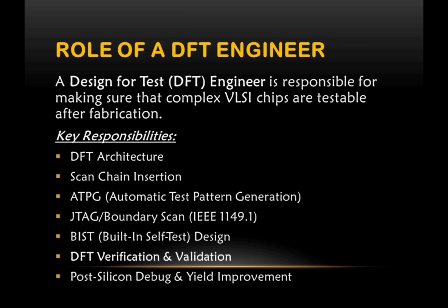The first responsibility is DFT architecture, which is planning testability features during the design phase itself. The next responsibility is scan chain insertion, implementing scan-based test methodologies using scan chain methods. The third one is ATPG, automatic test pattern generation, which is used to generate test vectors by applying inputs in order to get outputs, targeting stuck-at, transition and path delay faults.